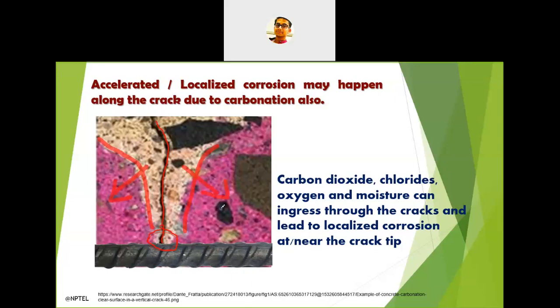If you see the permeability, in some cases it may be okay if the environment near the concrete system is quite prone to corrosion. But in normal residential buildings and in normal construction cases, the agents ingress the concrete system through these types of cracks only. So it is quite important to look after the cracks.